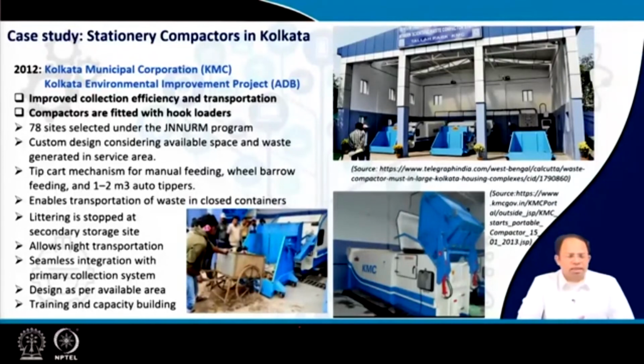Now coming to 2 case studies. The first case study, we will talk about compactor units in Kolkata. In this image you can see one compactor unit. It's just a storage container with an arm where people can come with wheelbarrows and tilt the wheelbarrow into this particular arm and mechanism where the garbage is stored, and this is lifted and put directly inside the compactor. Then some units of these compactors are stored in this particular enclosure, and as per the space available, the compactor sizes could be determined.